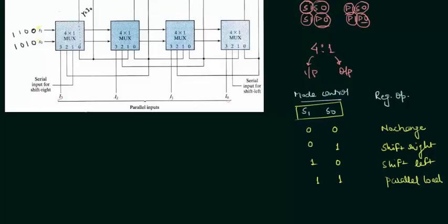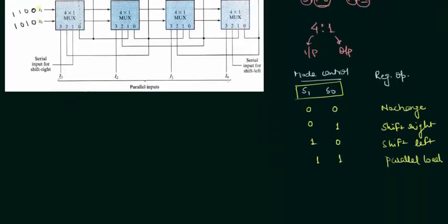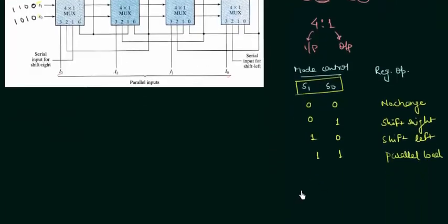The next thing is the D flip-flop. We are using the D flip-flop here, and you must know the table for the D flip-flop. I am going to make the table for the D flip-flop quickly. We have clock, we have D, the data input, and we have the next state Qn+1. When clock is 0, whatever the value of D, the output is going to be the same.